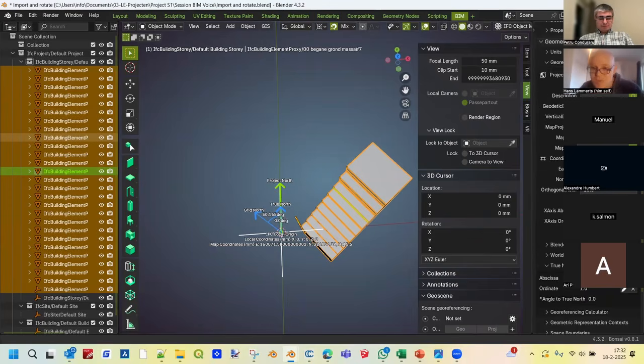If you have information that this is wrong, you can type the right values, like 60.0, and then you can save that as an IFC. So the IFC is editable using Bonsai, but it's the same if you are editing in a text editor, absolutely the same.